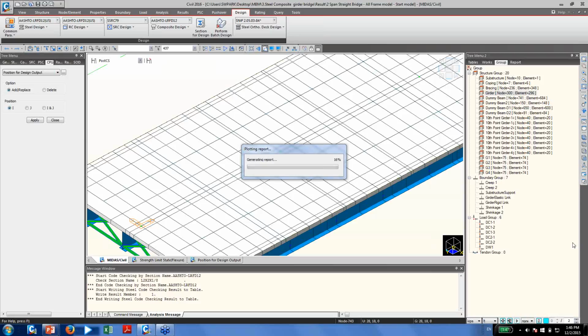So I got one more question. What is the difference between the negative and positive composite sections? As I mentioned before, for the negative composite section, I just assumed that the section is under negative moment, and the positive section is under positive moment.